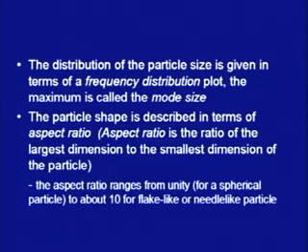Now, it is not important to know the size of the particle for a particular metal powder. As I have already said, there are different metal production methods, and they will make metal powders with different properties. Some of the metal powders will have very big sizes, some will have very small sizes. Similarly, the size will vary within one particular type of metal powder. Suppose we take a case of 100%. Out of 100%, 10% of the particles may be of one particular size, 20% of another size, 50% of a different size, and the remaining can be of a different size. So, the particle size varies over the total quantity of the metal powder. On the basis of what is maximum, we say this is the mode size of this metal powder: 50% of the particles are of this size. This I will explain with the help of some diagrams also.